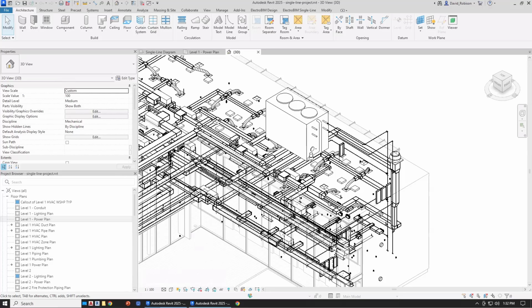You can choose to have Revit control the circuit descriptions if you want to. Revit has functionality for that. It has their paradigm for dealing with circuit descriptions. It's kind of based on the circuit having a description itself that's based upon what's connected, but it's really a circuit value. Or you can override that and use the ElectroBIM circuit descriptions.